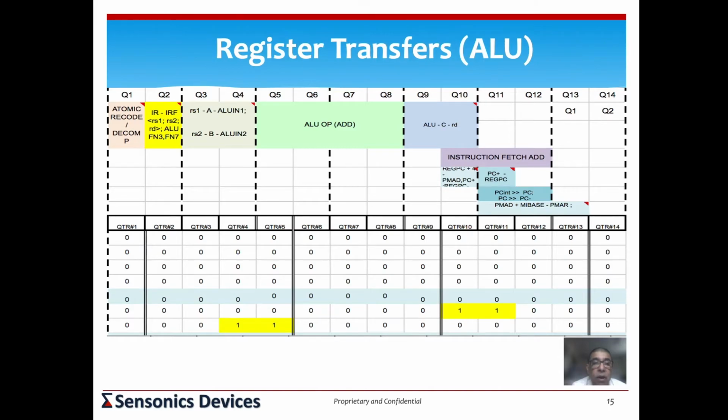Here our target has been that as many instructions as we can, ideally all of them, should have a throughput of 1 cycle. Meaning that if I put ALU ops back to back in the 3x3 matrix, if all are ALU ops, they should all function without any conflict, such that after an initial latency of 3 cycles, I should be able to get 1 instruction out at a time per cycle. So if you want to do that, then there are certain things that will have to happen in the housekeeping tasks. And that certain thing is what shows up in this PC plus PC.